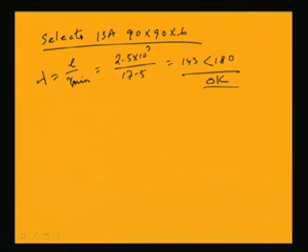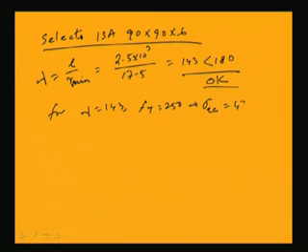Now, we will find out the allowable stress in the member for this particular member and the calculated stress. So, for lambda equal to 143 and Fy equal to 250, we can find out the allowable compressive stress sigma AC as 47 MPa. So, allowable stress we are getting as 47 MPa.